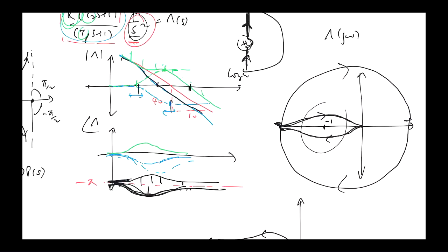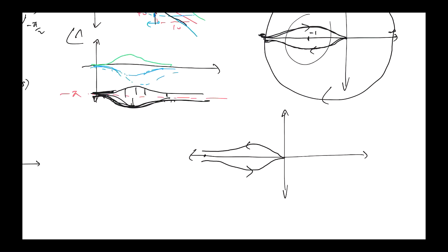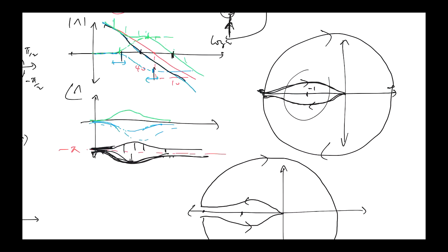Now we've got to go around the little indentation around the two poles. Okay, the same thing will happen. We'll get a net change in phase of minus 2 pi because there are two poles inside the little indentation. So as we go around the indentation, we get minus pi due to one pole and another minus pi due to the other. Minus 1 is inside here. How many encirclements do we have? 0. We don't encircle that point. We go around it, right? But we don't encircle it. Unlike this case here, where we definitely encircled it twice.